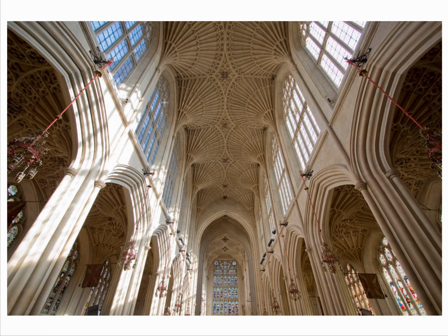And the really beautiful part about it is when you start to be able to trace the loads, we can see these isostatic lines of both the slab down to the column. Gathering it, umbrella, down and in. Each one of these force lines then comes in and concentrates into a column. This column comes down, but of course, now that the weight itself is doubled, with these arches that are coming in, the column itself gets bigger.